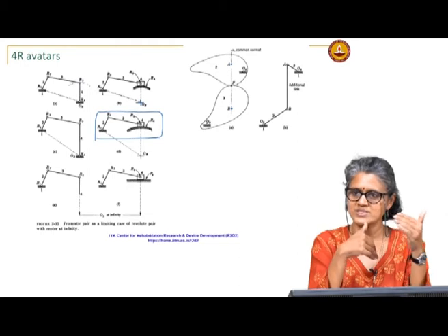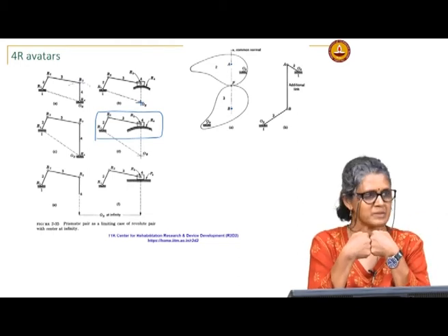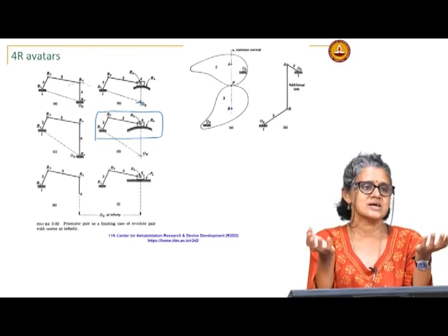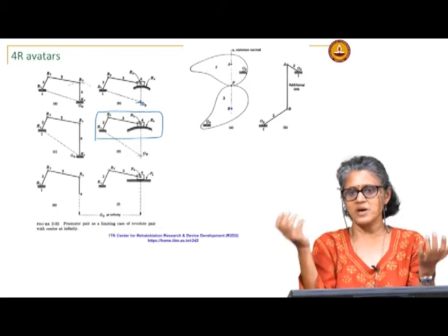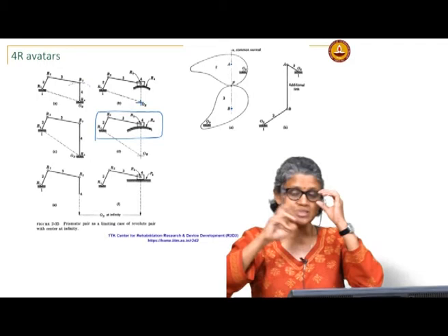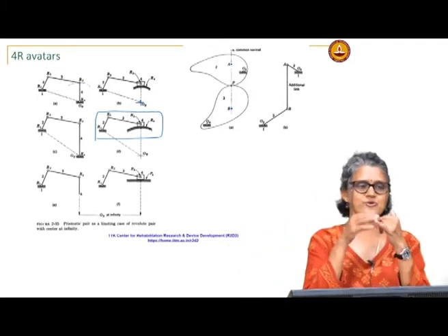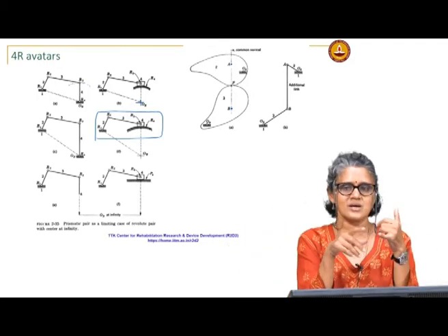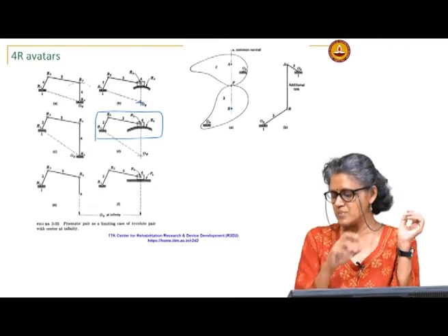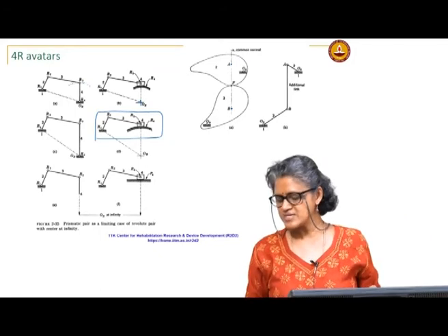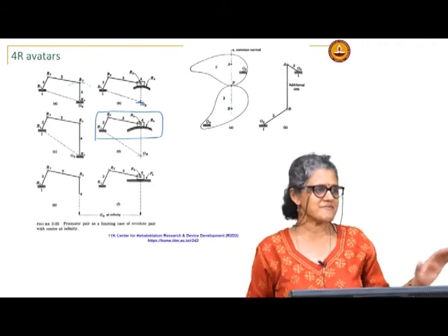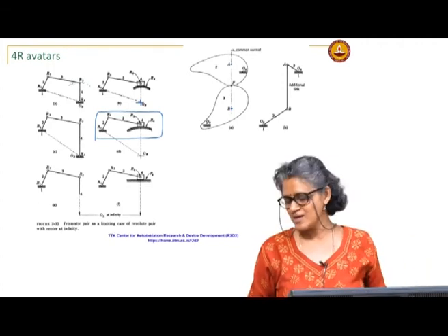With a cam follower system where the input and the output members are directly in contact, it is essentially a series of changing 4 bars, and therefore, you get a lot of flexibility in designing the input output motions. But cams of course have other problems, especially with respect to wear, maintaining contact between the links, etc. So, in some cases linkages typically are preferred, but of course again it depends on the application. That is the caveat everywhere, it always depends on the application.